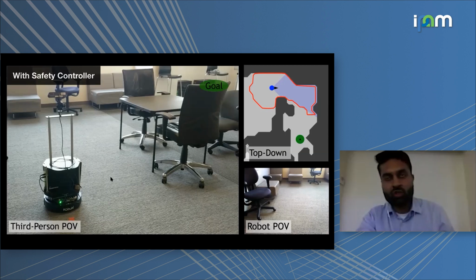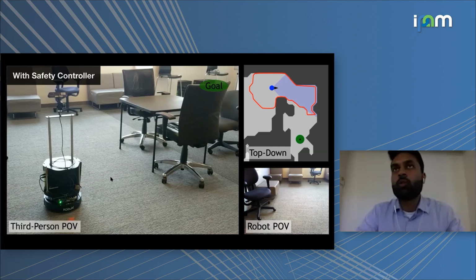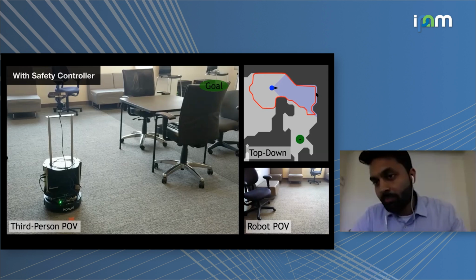The biggest difference between control barrier function and reachability is that control barrier function gives you only a locally optimal solution. In particular, when you have control bounds and disturbances, the Lyapunov inequality that we solve in control barrier function may not be feasible. And hence, you may not be able to maintain the safety. So what we are doing there is only computing an approximation of the backward reachable set and using that as the barrier function itself.